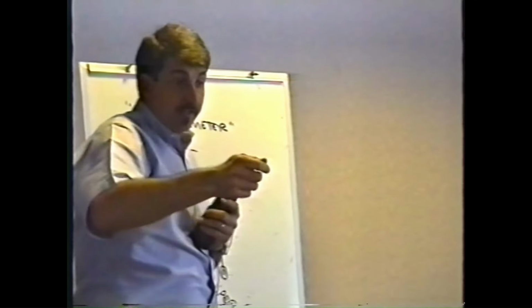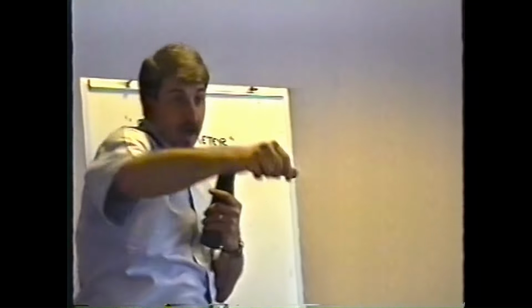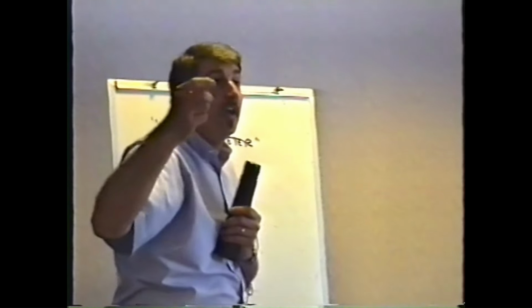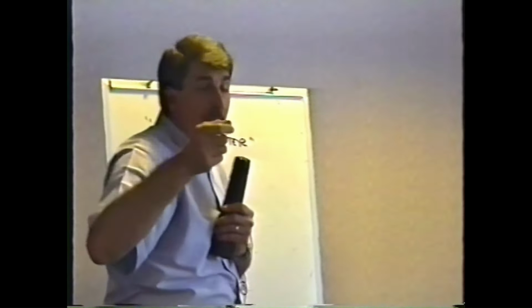Well, that's all it must have been. I just took the vertical size pot and rotated it back and forth a few times, and the picture was solid as a rock. When I put it back, I didn't put it in the exact same position. I moved it over just a little bit, making the picture just slightly small, which I don't mind seeing, a little black on the tops and the sides of the picture personally. And it was fine. That's what he should have done out in the field.